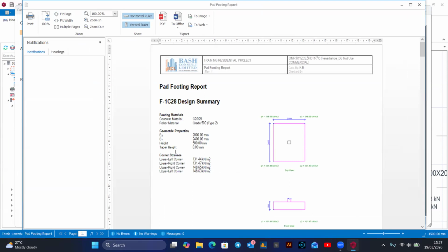There is no minimum diameter. Okay, the minimum is there because now you cannot put R8 or T8 like as longitudinal reinforcement in the footing. That is shear steel. So when you're designing, take it that the least diameter of reinforcements or longitudinal steel that you can have is a 12 millimeter. Okay, so there is no limit for maximum, but what will constrain your maximum rebar diameter, it will be the cost constraint.